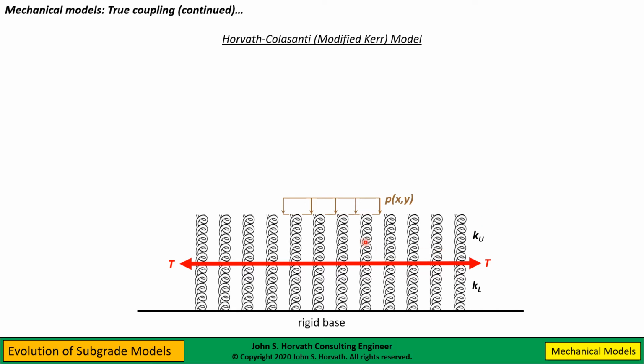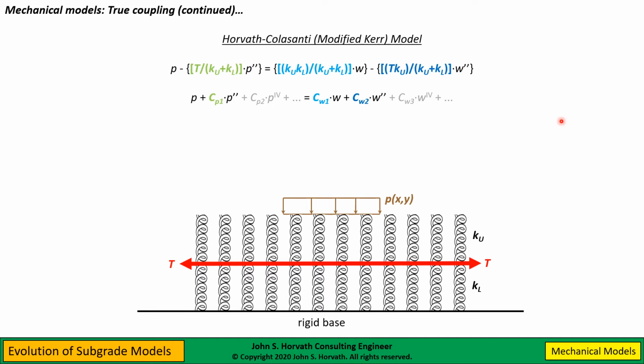Again, it's important to keep in mind these models go on to infinity horizontally in both the x and y directions. And it would be nice, certainly, when you put this into a structural program, to be able to truncate the model at the edge of the foundation. You don't want to be modeling this to infinity, obviously. So very few researchers have come up with the appropriate boundary conditions. Regis and I certainly did this. Again, you see relative to the Poisson solution.